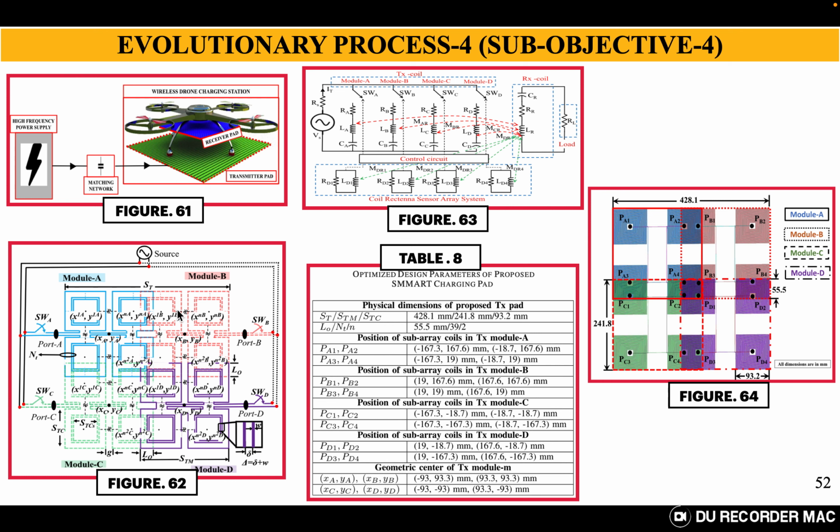Now also, you may get a doubt that in the literature there is a similar kind of work with 4 coils overlapping with each other. So what is the difference? The problem with that literature design, because we are comparing all results with that design only, is that the voltage uniformity is poor, or we say the misalignment tolerance is only 32.4%, compared to what we are achieving in this design, which is almost more than double, with reduced dimensions. So we also reduce the dimensions drastically.